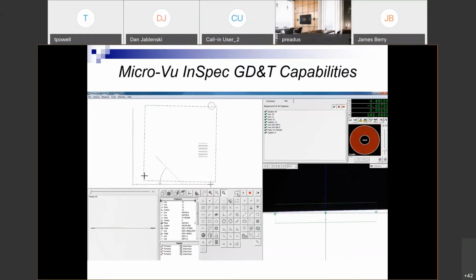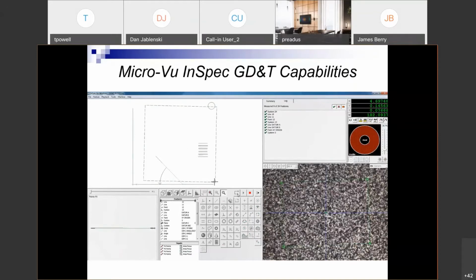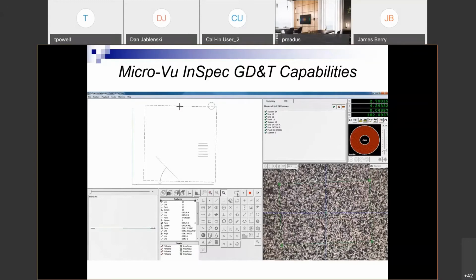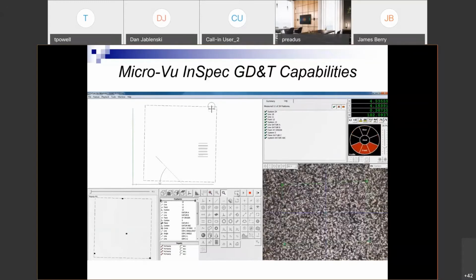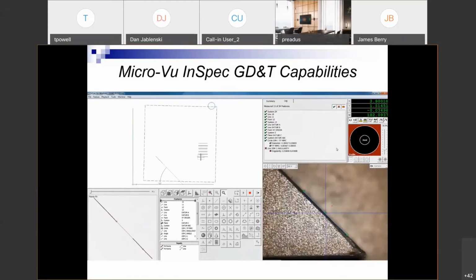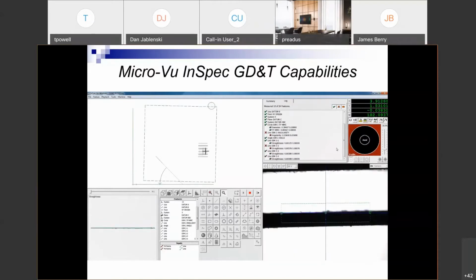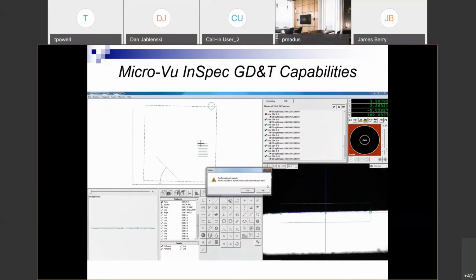Now it's measuring the datum structures on the side of the part, A and B. Now I'm using area focus to measure the top plane on top of the surface for my datum C on this part. Then quickly, it's measuring the outside diameter on that post and an edge for angularity. If you see up in the log view, it's measuring all those lines and reporting straightness. We got some straightness that's out on those points, probably because of the flash that was on the part.